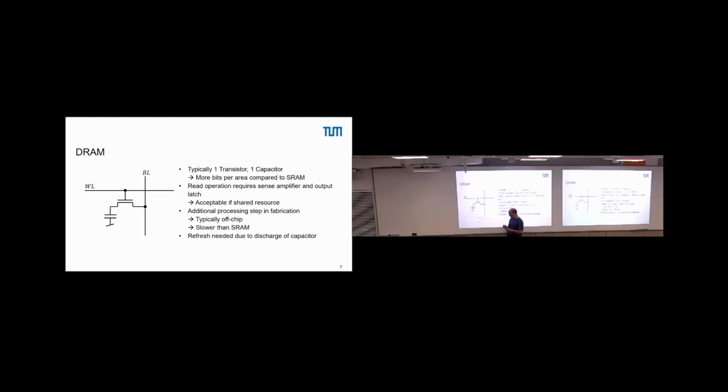Now, if you add the sense amplifier, then maybe I take this one here. Then we would have, I just write SA for sense amplifier. This one here would be amplified somewhere to VDD. This here would be amplified somewhere to ground. So this is just the sense amp, sense amplifier. So what does this mean?